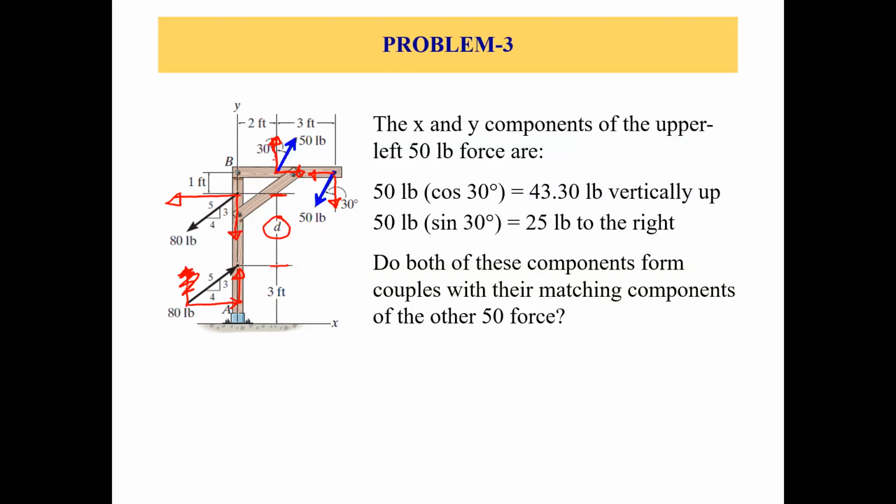So now if you look at these blue 50-pound forces, which components are creating a couple? The vertical forces, the Y components, are creating a couple, because the X components do not have any perpendicular distance between them. They are passing through each other. So that's why they are not creating a couple.